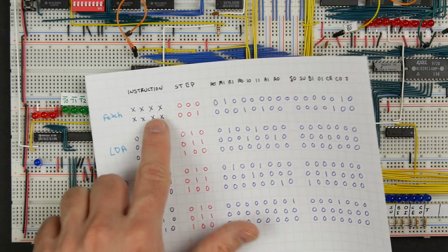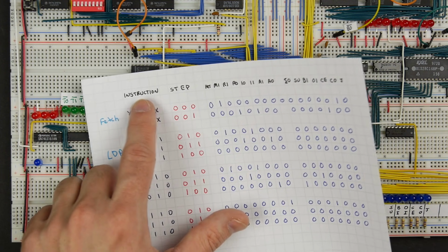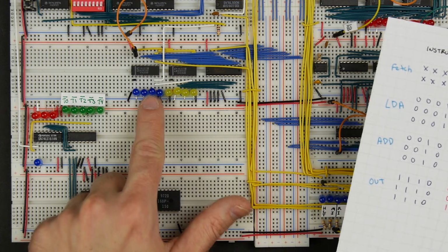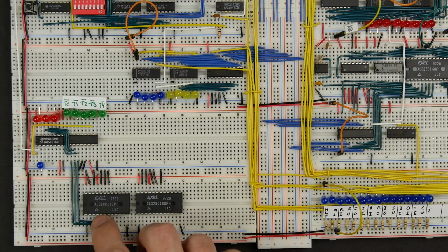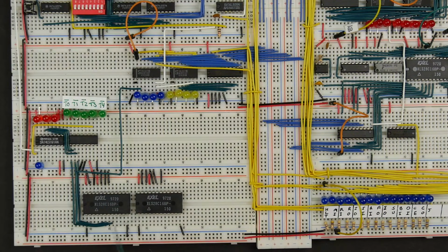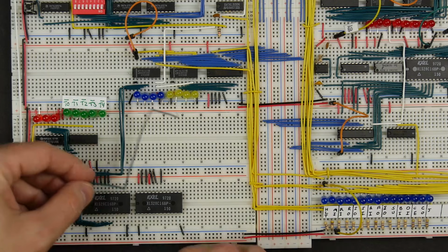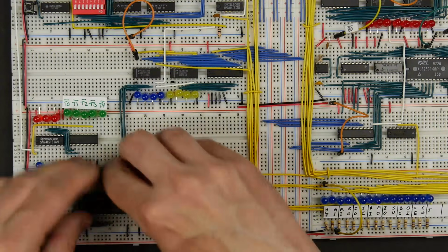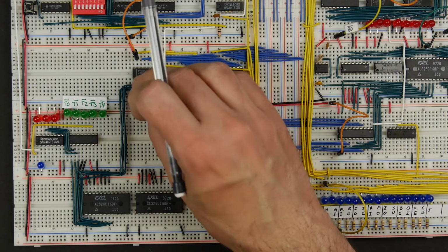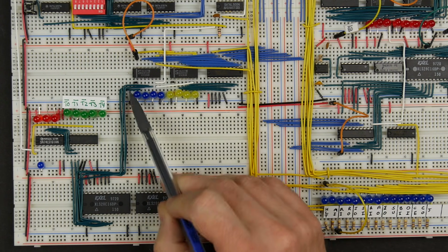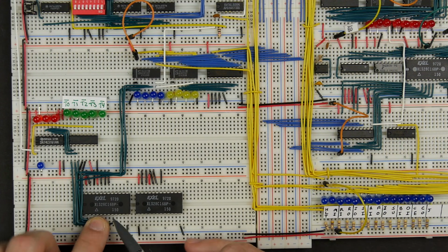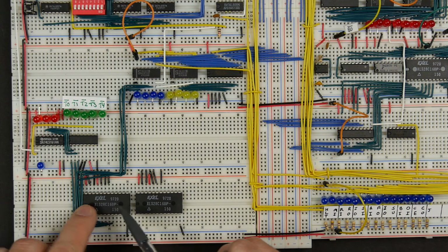So we've got the first 3 address bits hooked up to which step we're on. So those 3 bits. And then the next 4 address lines are going to go to the instruction, these 4 bits here, whatever instruction we end up loading. And so there we've got the 4 bits from the instruction register that indicate which instruction we're executing, now connected to 4 of the address lines for this first EEPROM.